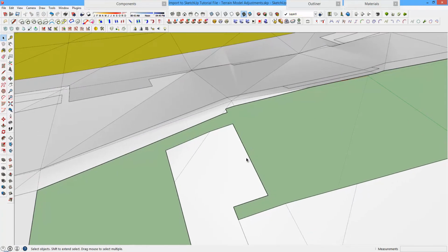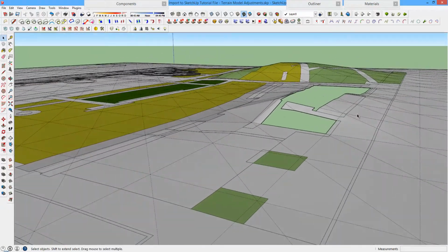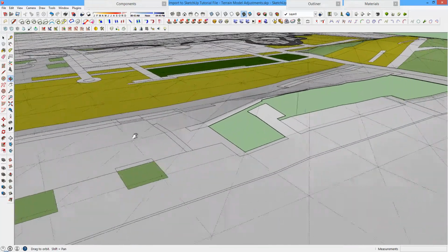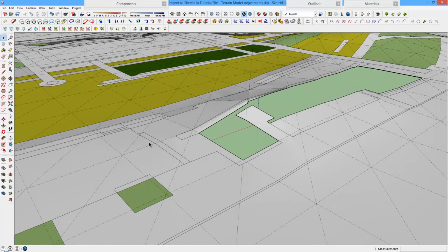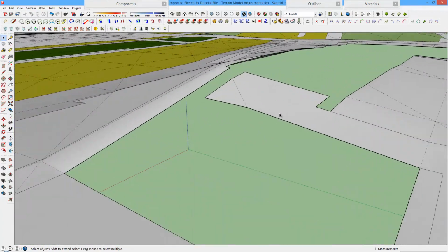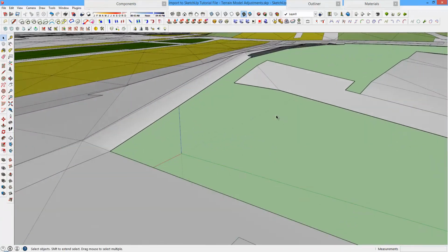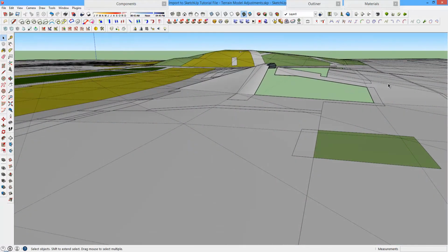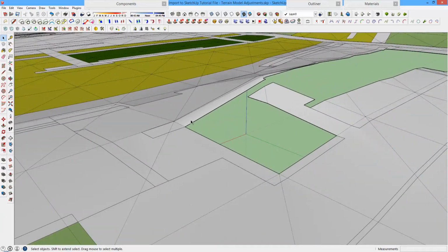Because what I need to do is, if I can get this sidewalk leveled out and this edge along here leveled out the way I want it, then I'll just rebuild the surfaces there, and it doesn't take very long to do. Much easier than trying to move all those corners and points around. So let's start by kind of setting this sidewalk that comes in along from the front sidewalk. It's the entry walk to the maintenance building. So if I can get that set at the right level, then I can cue everything else off of that.